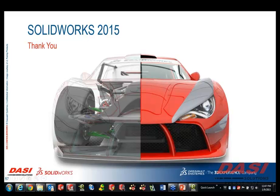So regarding plastics, can you model the likely warpage and then use the warped model for your tooling? You know, I have to actually check on that one, Sean. We have a thing in our other simulation tools where you can save the deflected model. So if you do have a displacement in a static simulation, the deflected model could effectively serve as a nice interrogation piece for what would be springback. So when it comes to the plastics model, though, it's going to tell you where warpage will occur, but there's not necessarily a displacement or a warpage simulation taking place there. So it's more or less feedback, not actually showing you the warped change. So my guess is going to be no, but I can check into that one.